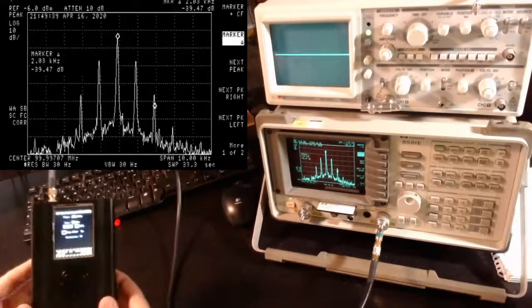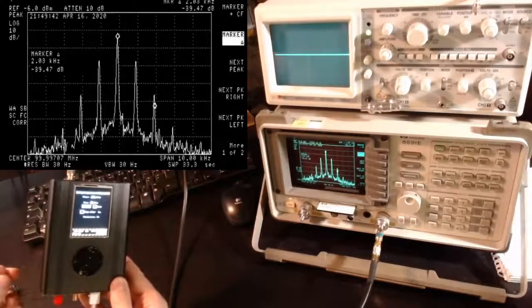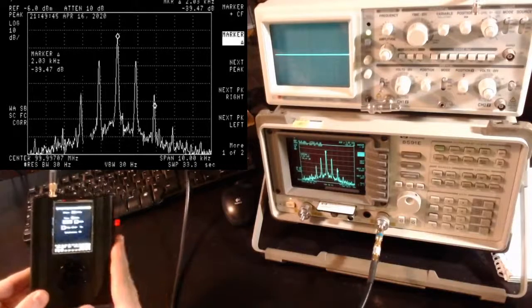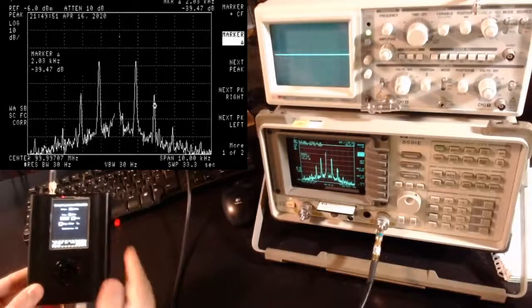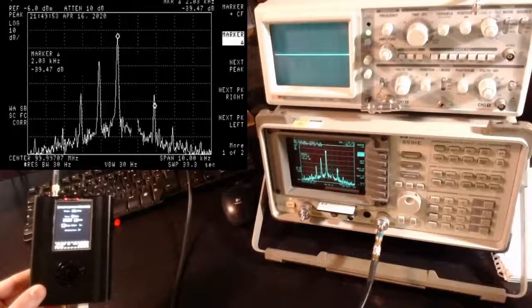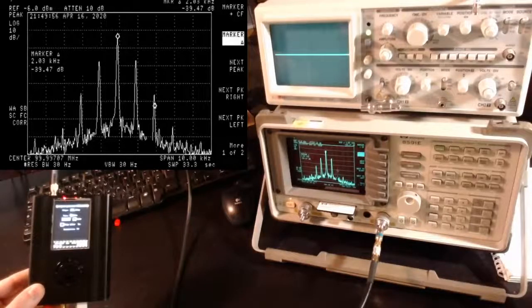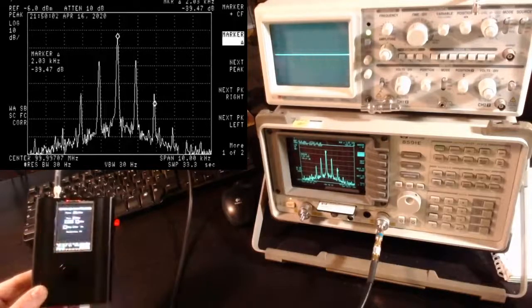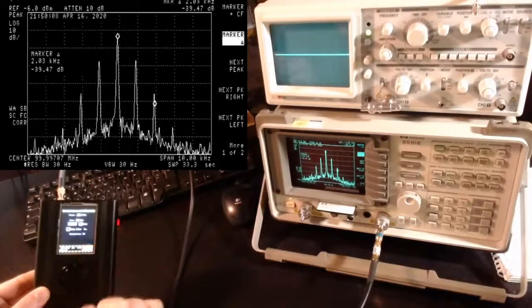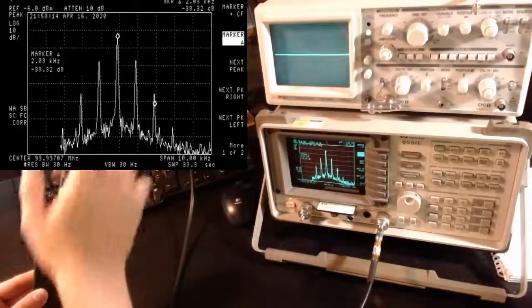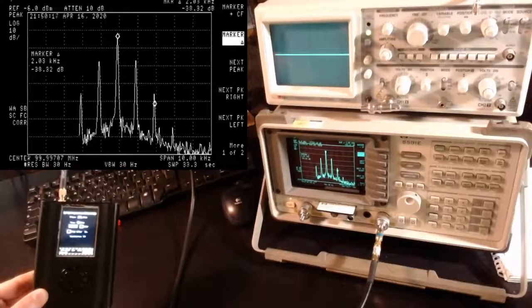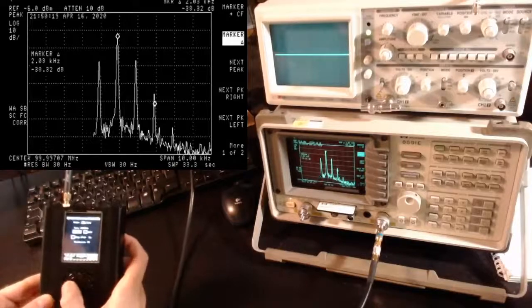so this is just to show you one of the many functionalities of the Portapack. We have a shield on top of the HackRF, and we can use it to have very quick access to the functionality of the HackRF as a signal generator. You see how quick it was to change frequency, to change amplitude, and to change what is being modulated and stuff like that. So let me stop the HackRF. By the way, before unplugging the HackRF, never do that while it's transmitting, because you risk frying it. You really risk frying its front end.